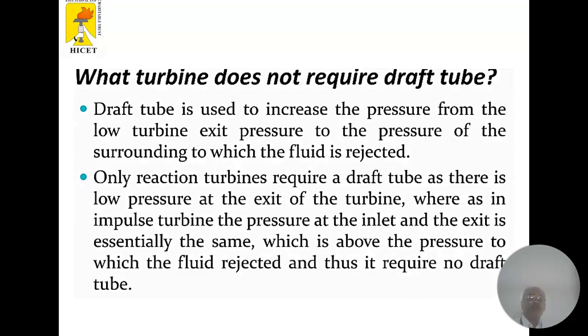And what turbine does not require a draft tube? It is used to increase the pressure from the low turbine exit pressure to the pressure of the surrounding to which fluid is injected. Only reaction turbines require a draft tube, as there is a low pressure at the exit of the turbine, whereas in the impulse turbine, the pressure at the inlet and the exit is essentially the same, which is above the pressure to which the fluid is rejected, and thus it requires no draft tube.